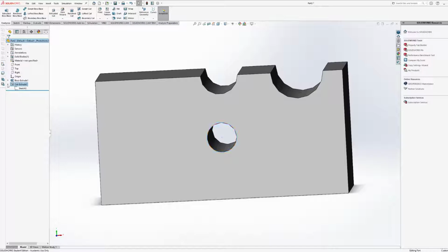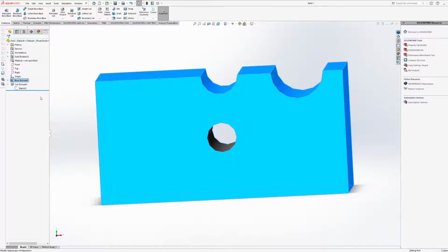What we can do is, if you click on that little drop down, this is where it's a little bit important to understand what's what in your feature tree. But usually things are pretty defined. When you hover over specific features, it'll outline what that feature is in reference to in orange. So when I mouse over the Boss Extrude 1, and you can rename things, you just right click and then rename tree item.